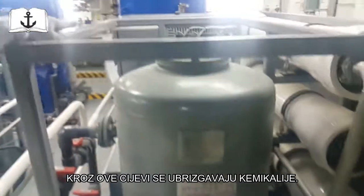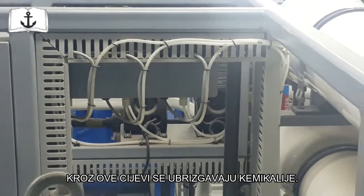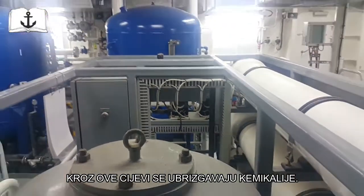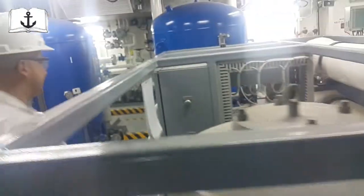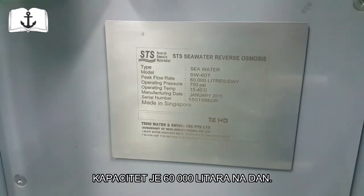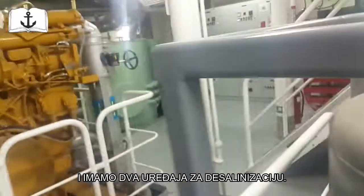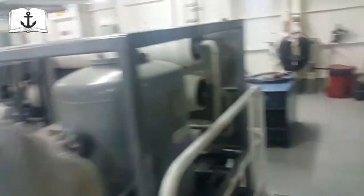Also, you have these small hoses for dosing chemicals like hypochlorite, so that the water is good for drinking. The chemicals you put in the water kill bacteria, chlorine and stuff like that. You can make, I think, 60,000 liters per day. That's 60 tons. It's a lot, and we use a lot also. And we have two of those units, so 120 tons of water we can load. And you can run both together, correct? Yes, you can.